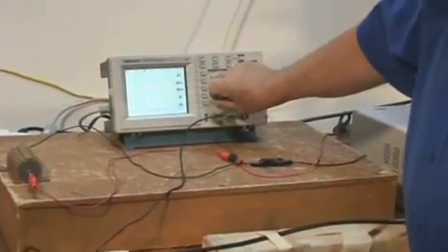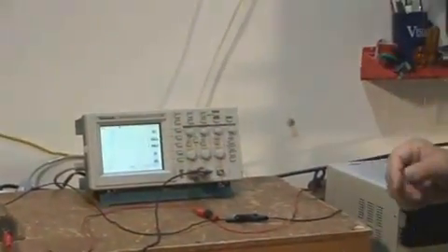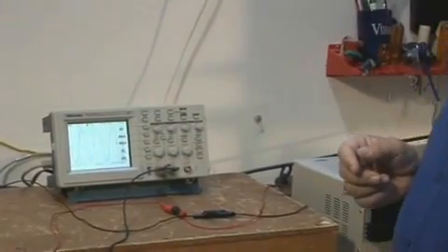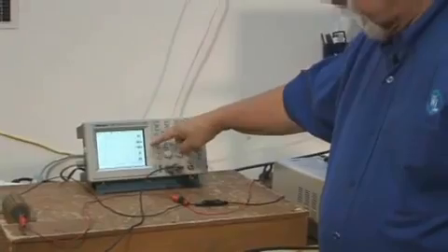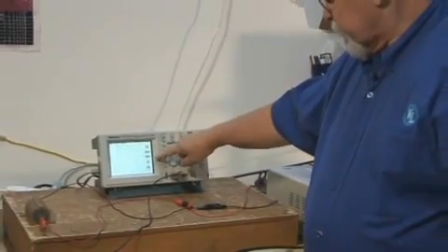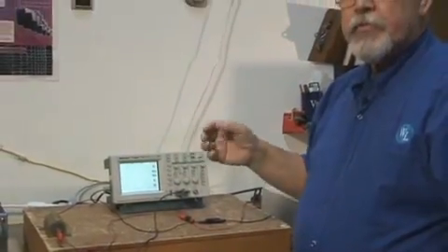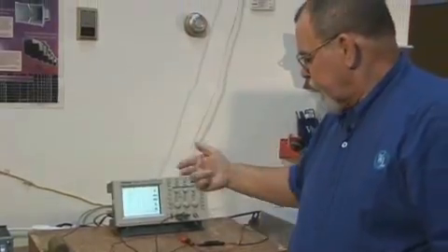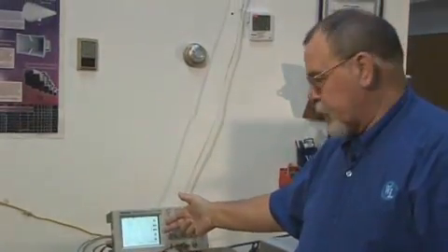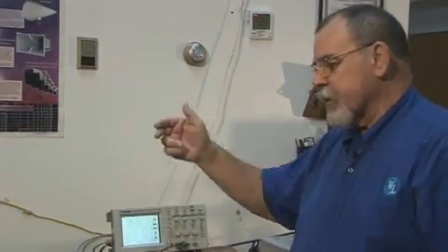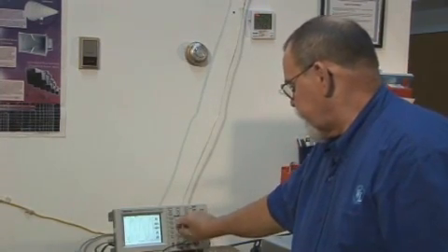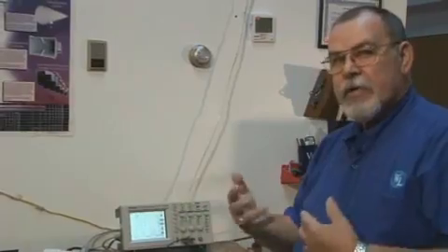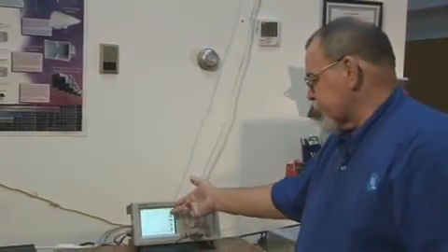Let's get to the point where we can actually measure this, and you'll find that this is a 60 Hertz primary power. When we were doing the calibration, we were using the measurement circuits here to determine what our applied voltage is. Obviously, that's not going to work now because it's going to keep measuring the 120 volts being applied. So that's going to be my primary problem, is I have to measure my signal in the presence of that signal.